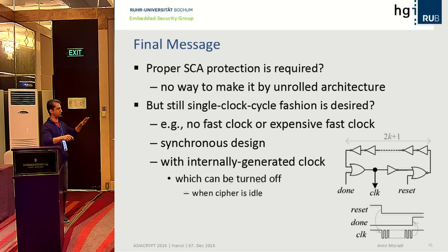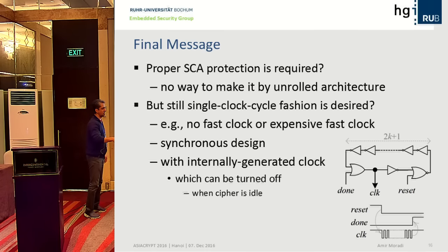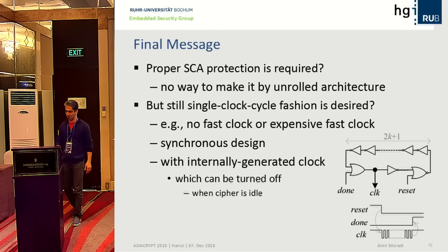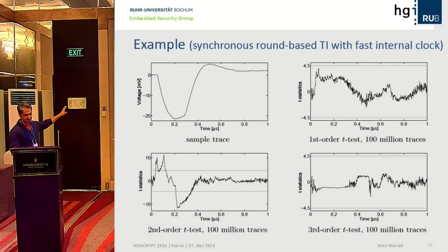This is the engineering part, probably completely out of the scope of the crypto, but you can generate the clock internally in the system and then have just some control signals to say that this ring oscillator should start and when it should stop working. Then, without any external clock, which is always working and consuming energy, you can implement and run the system. As a last slide, I have run out of time already.